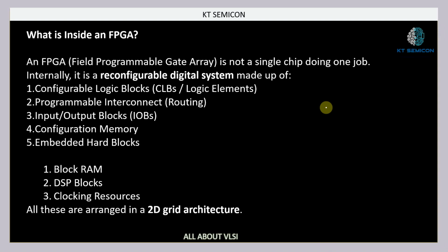So basically, FPGA stands for Field Programmable Gate Array. This we already know, and this particular FPGA is not a single chip doing one job. Internally, we have a reconfigurable digital system, which is made up of something known as configurable logic blocks or logic elements.